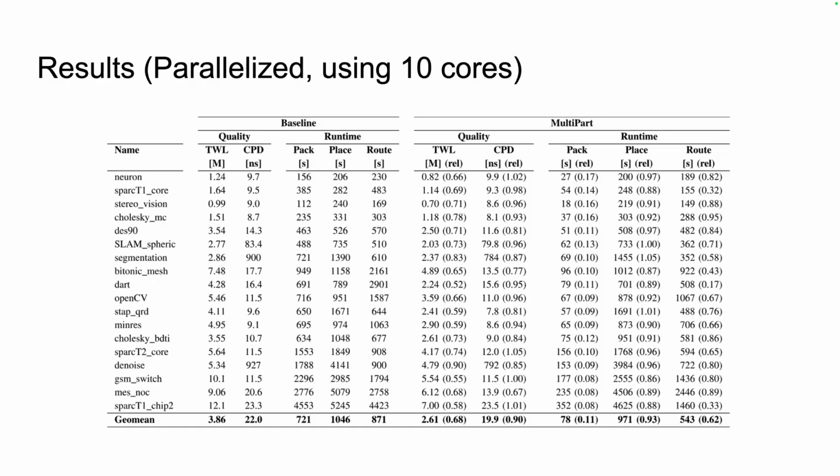And so I did basically the same thing. I didn't use hMetis and I didn't use recursive bipartitioning. I used graph partitioning to do a minimum cut and told it, hey, give me 16 partitions. So I didn't do two partitions 4 times. And I did not get the same results. I could not recreate these results. And I feel like that's because my baseline is VTR9 and theirs was VTR7.